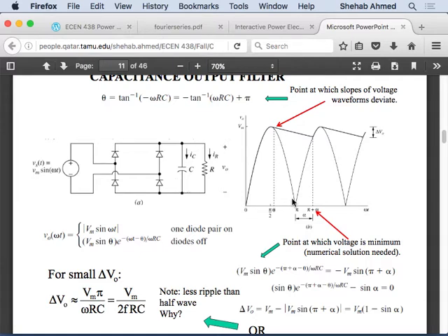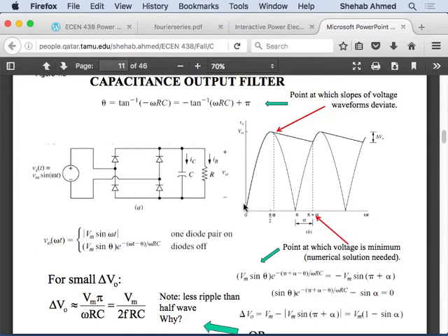Remember we talked about the effect of frequency. So here in a full wave rectified waveform, I have doubled the frequency of the voltage that is being filtered by the capacitor. What voltage is being filtered by the capacitor? The full wave rectified waveform. Right? So the waveform here is without the capacitor. And then we've added the capacitor. What does the capacitor do?